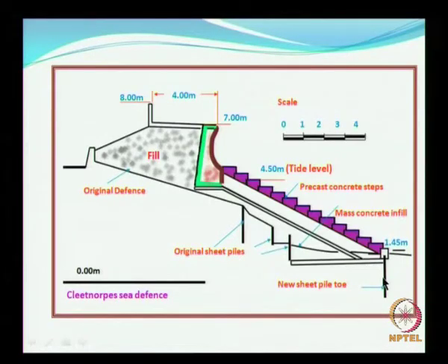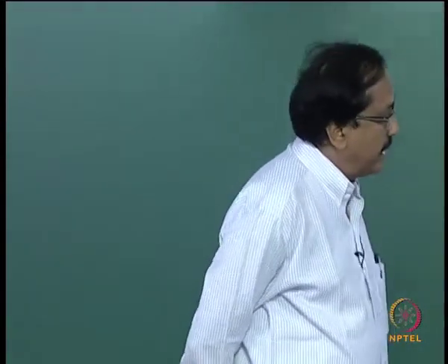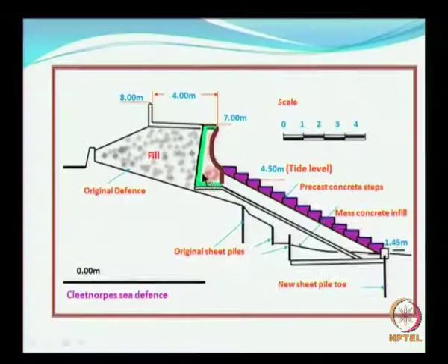Okay. Now, in addition, there are some sheet piles in order to retain the sand, particularly when you have the backwash. But these sheet piles are quite expensive, so people do not prefer them, and instead they use what is called a geosynthetic material, which I have already explained earlier and which will be explained again later.